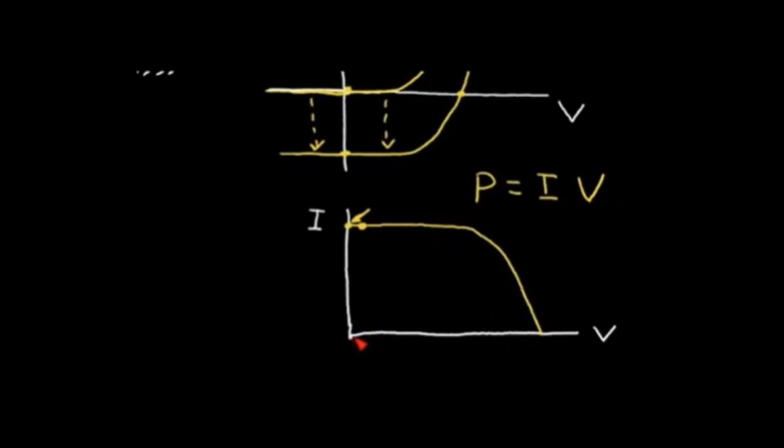So we've in effect shorted out the solar cell, and we produce a large current. But since the voltage is 0 in this equation, we don't really get any power, so it doesn't do anything useful. Now let's look at this point over here. At this point, we have no current flowing in the solar cell. So the circuit is open, and we're looking at a high voltage. But since our current is 0, we extract no power, so that's not very useful.